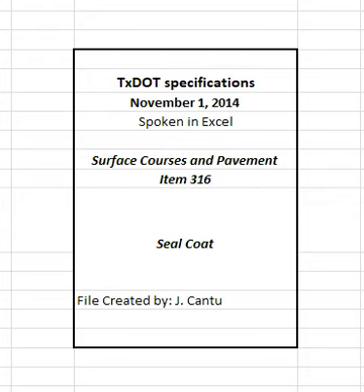4.5 Mixing hot AR binder. If using asphalt rubber, mix in accordance with the approved blend design required in section 316.2.1, asphalt. At the end of each shift, provide the engineer with production documentation, which includes the following: amount and temperature of asphalt cement before addition of rubber, amount of rubber and any extender added, viscosity of each hot AR batch just before roadway placement, and time of the rubber additions and viscosity tests.